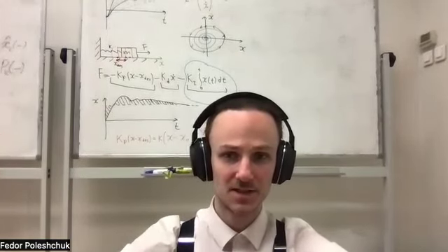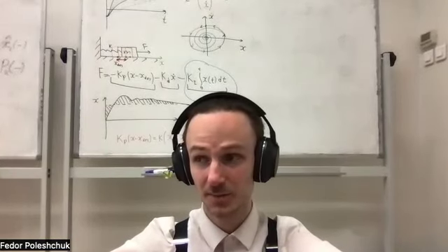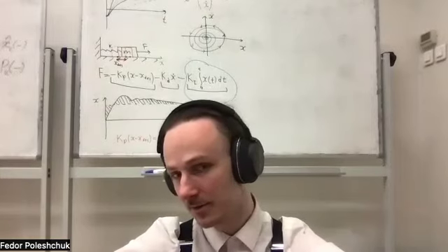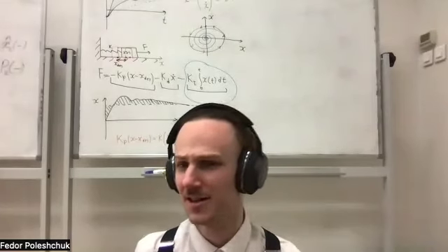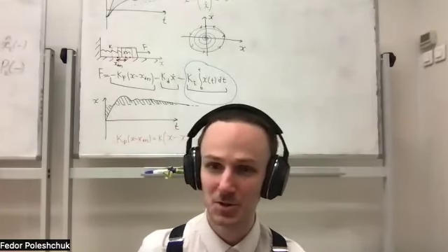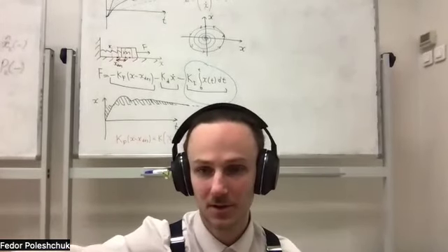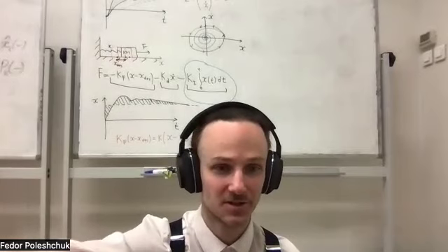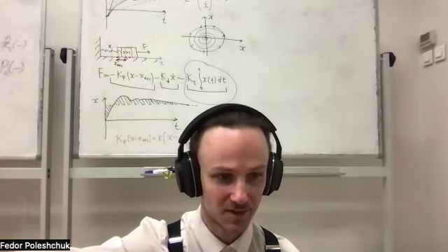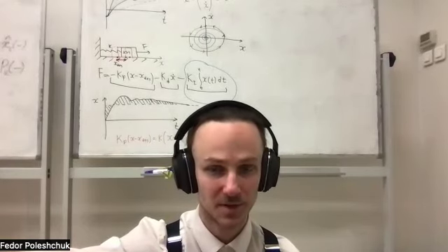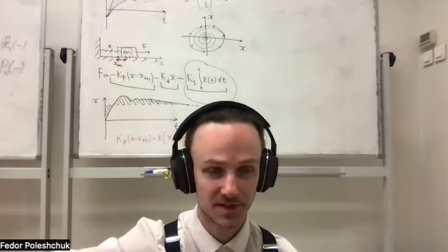The cool thing about PID is that you can tune it by just measuring the output. You don't really need to know exactly what's going on in the system. So it could have some friction, it could have some non-linearities, it could have anything. And you can tune it by just knowing what's going on after you have applied a certain controller, especially in simulation. However, it is difficult to formulate this controller for it to optimize some kind of objective, which is really important if you want to, say, minimize energy.